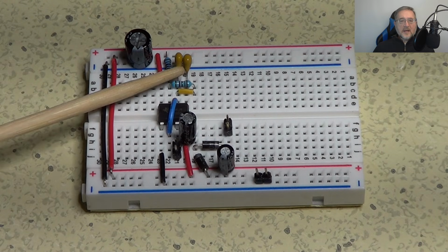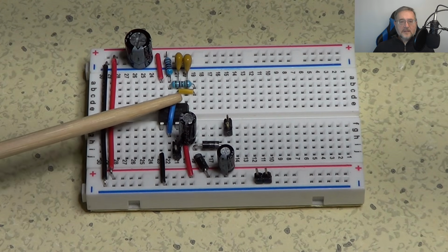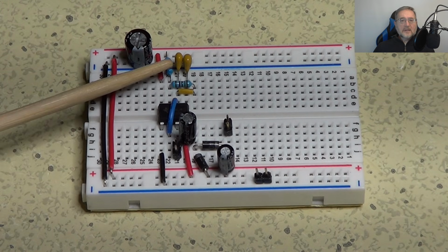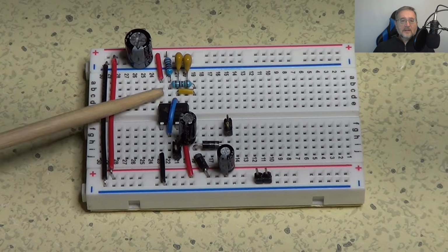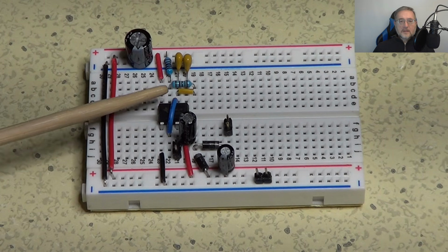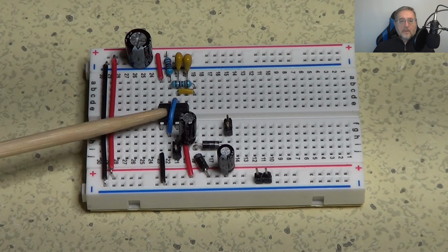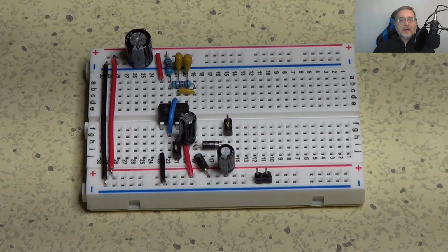This capacitor on the right is the one that basically filters the reference voltage on pin 5 of the IC. The other one is the 100 nanofarad capacitor that, along with these 2 resistors, provide the timing for the 555. The signal, like we said already, will be a square wave with a duty cycle of about 0.5 or 50%.